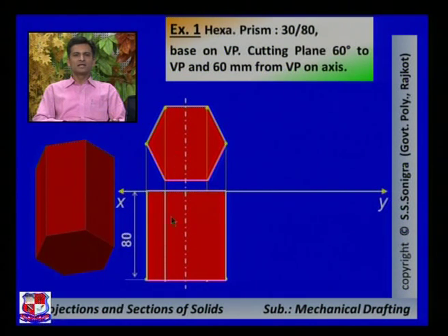Now these are the projection lines. This upper edge, these two edges will be visible. So from these two edges draw lines. These two lines represent this upper edge, and these lower edges will not be visible, hence hidden lines are there. So two lines are there, solid line and hidden line, and priority should be given to the solid line.